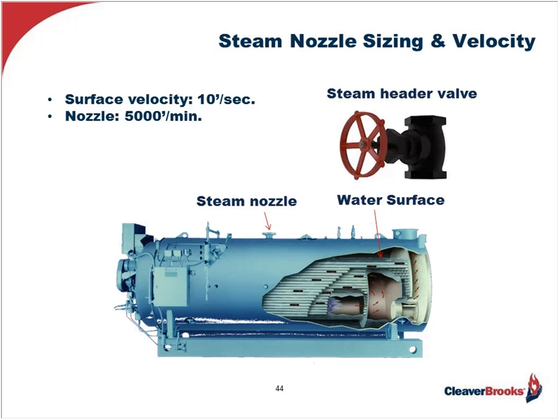The issue is carryover, whereby boiler water is actually sucked up into the nozzle and into the steam system, causing wire drawing and seating problems with the header valve and possibly water hammer throughout the piping system. And this can be very dangerous, water hammer.